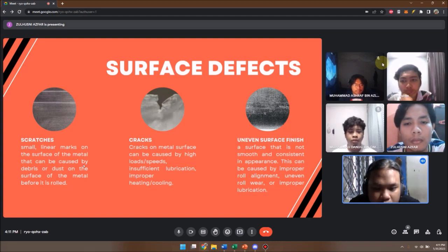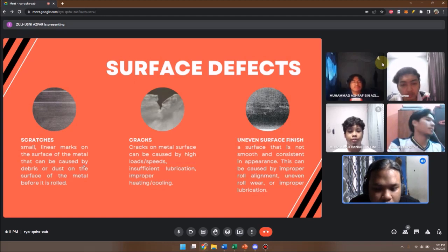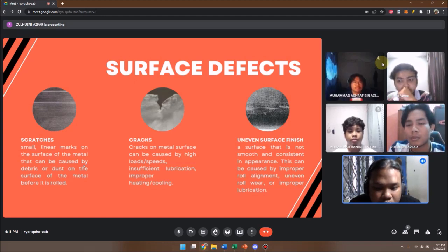Cracks can also be caused by improper heating or cooling conditions. While uneven surface finish refers to a surface that is not smooth or consistent in appearance. This can be caused by improper roll alignment, uneven roll wear, or improper lubricant. Next.